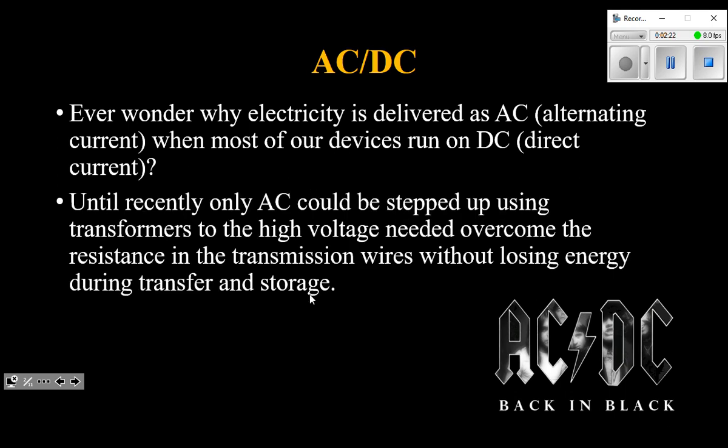So when we have a power plant generator down the road, like we do at Milner, when they produce electricity, if they didn't step up the voltage to a very, very high voltage, which reduces the current down to a very, very low current, then the higher current as it traveled through the wires, even just to get as far as Grand Cache, never mind to get to Calgary or to Lethbridge or to High River or anywhere else that they might be sending the electricity, the resistance would be so high that the energy would be used up and lost as heat. So we'd be heating the air around those wires very well, but we would not be getting electricity actually transmitted.